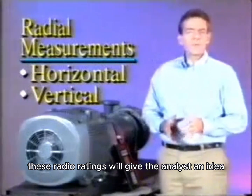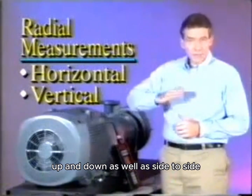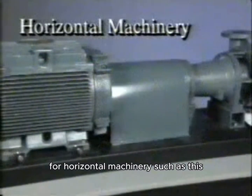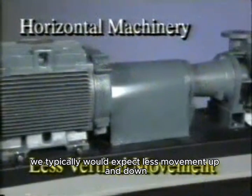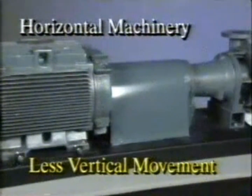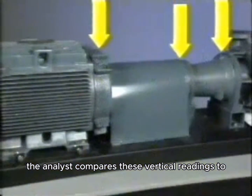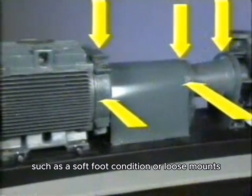These radial readings will give the analyst an idea of how the machine is moving up and down, as well as side to side. For horizontal machinery such as this, where the mounting is at the bottom, we typically would expect less movement up and down because it is limited by the mounting. The analyst compares these vertical readings to the horizontal readings to check for problems, such as a soft foot condition or loose mounts.